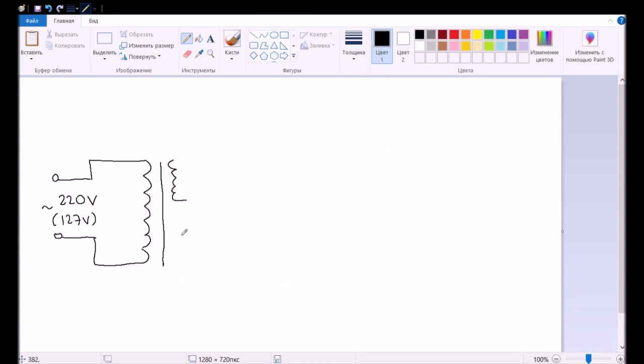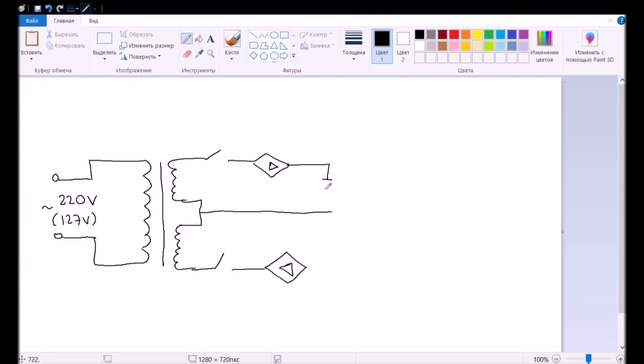Let's use two secondary windings. And we will talk later how to construct such a circuit. Now we have a switch and rectifier in each branch. These windings should be connected in series, and in the lower branch we also have a switch and rectifier. It works backwards, so we have negative voltage in this branch, and the intermediate point is also laid out.